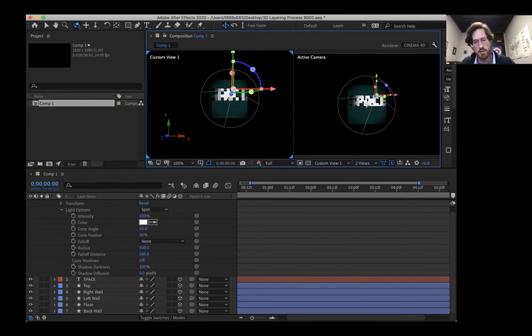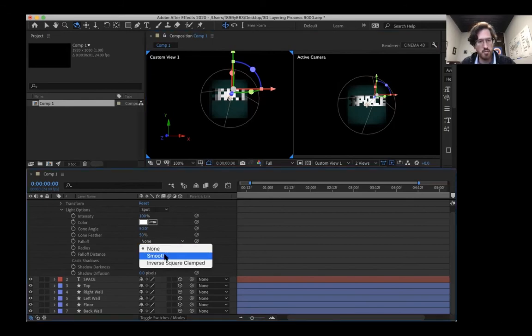And you can actually do that if you change some of these falloff radius distances and turn on cast shadows. So if we want this to be kind of smooth, we can set that. The radius is here. You can change those settings as well. The falloff distance will give you, as before, where the light starts not casting in depth space. Right now, our light is very, very close to our object and we've kind of stopped it from going anywhere within the box. So you may not see much difference when you change those numbers.